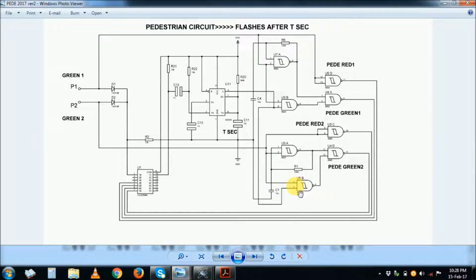It means any low here, we don't care about the other one. So low here, you have a high here. And remember, this is a high, and also this oscillator output is a high. So you have a high here and a high here. Here is a low. A high and a high on the NAND gate, the output is a low. Here you have a low, a high output, you have a low output, so it is red here and is off.